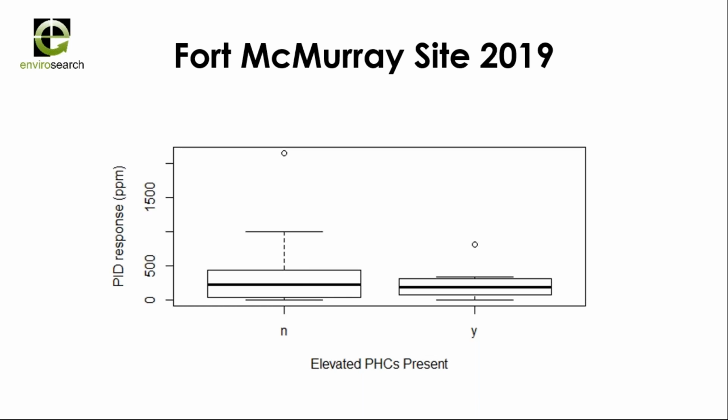This isn't to say a PID is never going to work, right? Again, it comes back to if you're talking about a sample with volatiles, especially fresh volatiles, that's a different story. But on these two sites, they are both weathered diesel and winter conditions, and those two things combined created the perfect conditions to get the poor PID response. So I think it highlights that you've got to make sure you're selecting the right screening tool for the job, depending on the contaminant in question. And the PID is definitely not the right tool for every job.